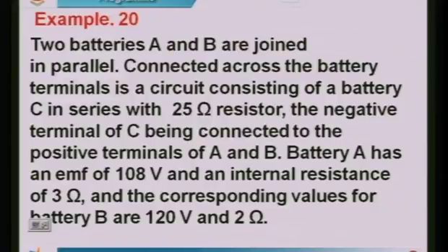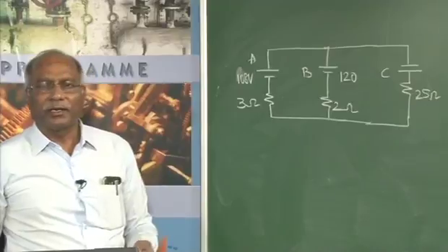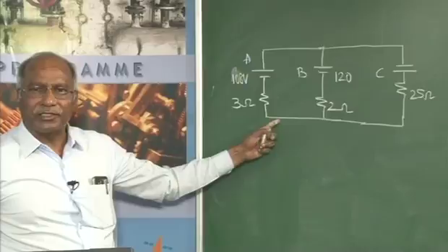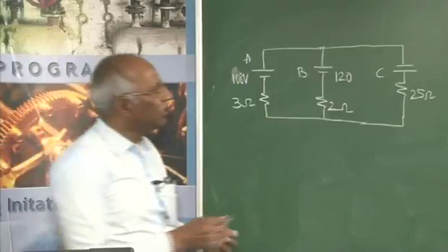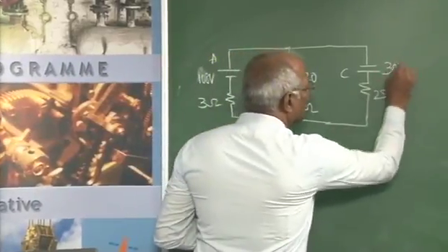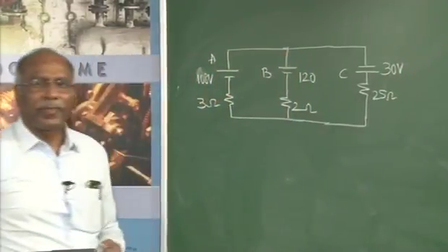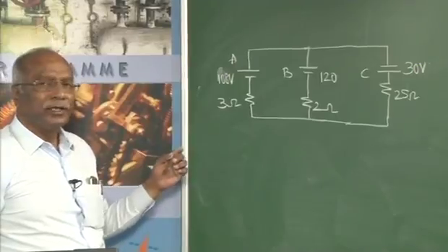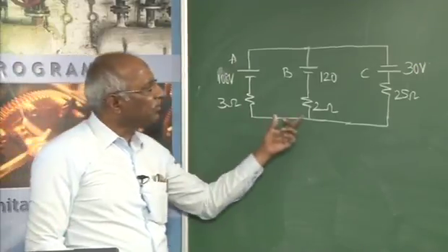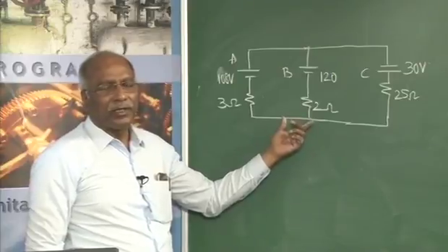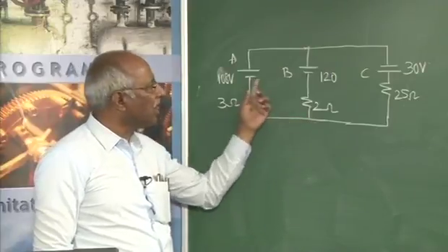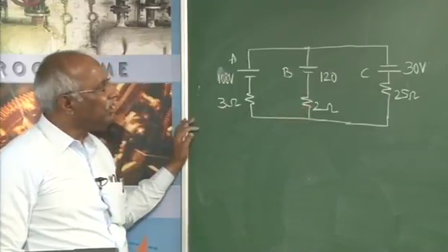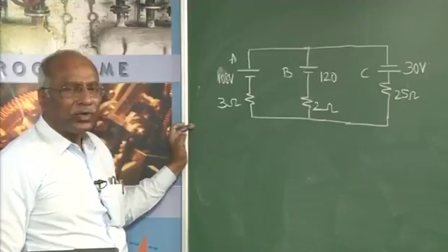and B. So, what has been given here has been converted into a sketch. The statement has been converted into a sketch, and C has a voltage of 30 volts with an internal resistance of 0 ohm. Determine the value and direction of the current in each battery. So, in that respect, this cannot be simplified using the network reduction techniques, because we have the battery sources or batteries along with the resistors. The only way is to consider the loop equations.